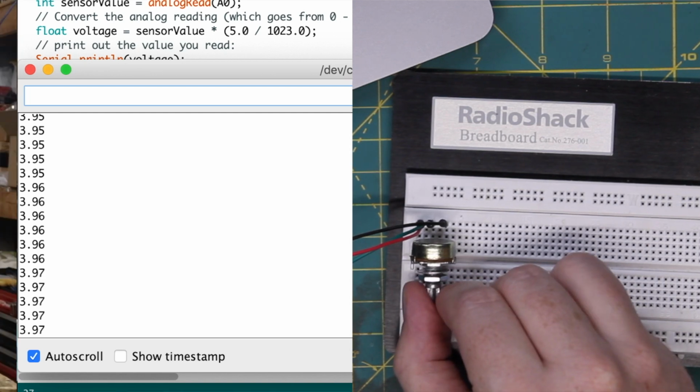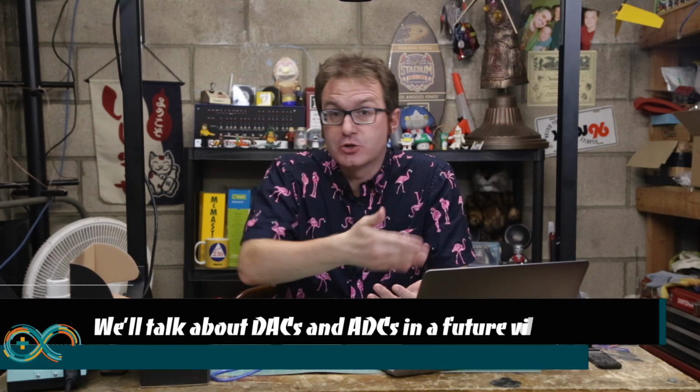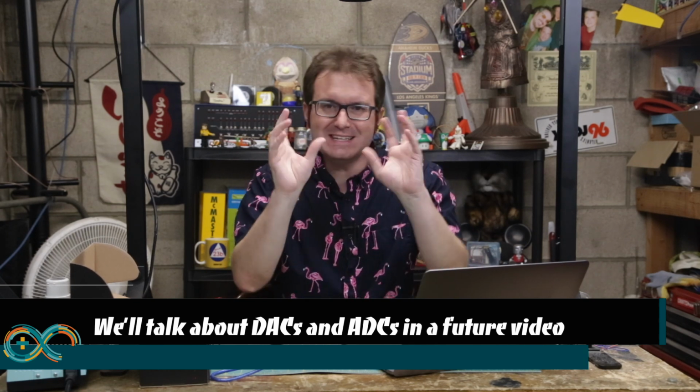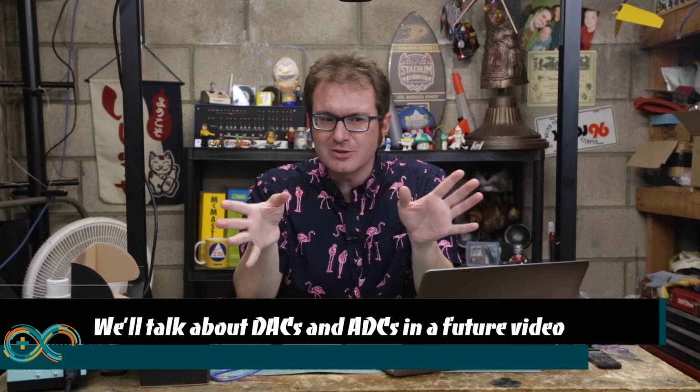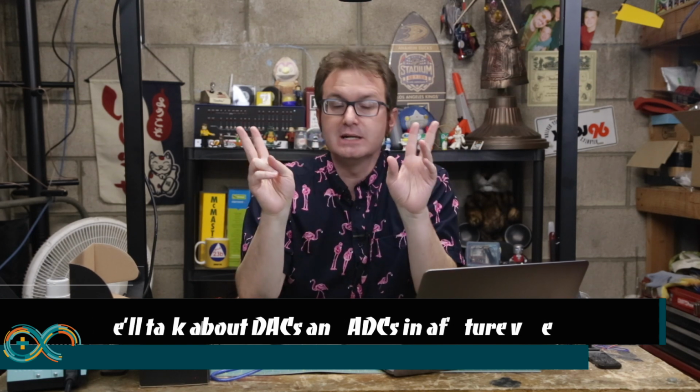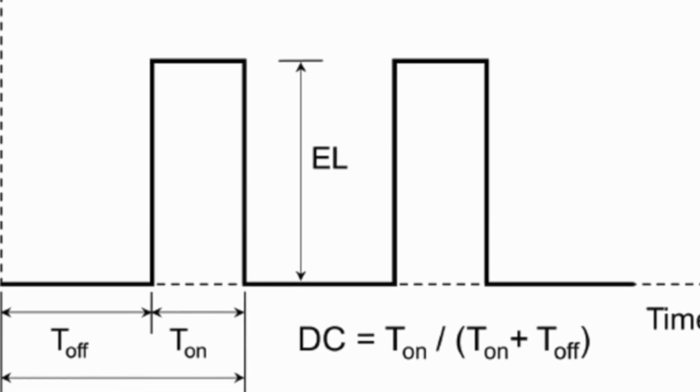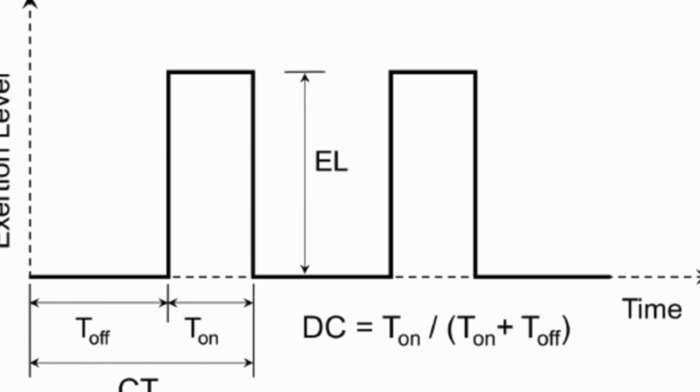In our previous lesson, we learned how Arduino can read analog values, no problem, but it has a little bit of trouble writing analog values. And that's because it doesn't have a digital to analog converter. So it kind of fudges the values a little bit by controlling the duty cycle of the output on a particular pin. So what happens is its digital control, its on-off, its binary state, is used to create a square wave, which is a binary wave, full on, full off.